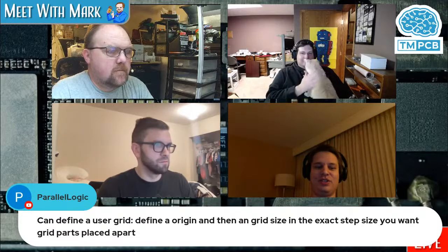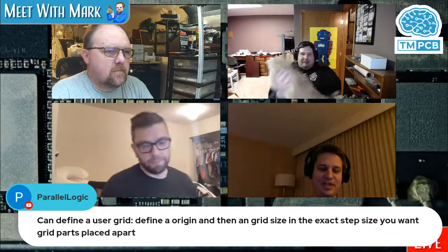So what I did is put the origin of my board at 0, 0, which is outside of the page, the title block. But yeah, that's the hardest part, is moving individual components. Actually not so bad, because you can just say go to this exact position. And you can rotate at the same time you move, which helps for me. Mine are arrayed in a circle. So I was able to say move to a consistent 10, 0 every single time. But then it would also add a rotation about the origin of 45 degrees, which would move it and rotate it all in one step.